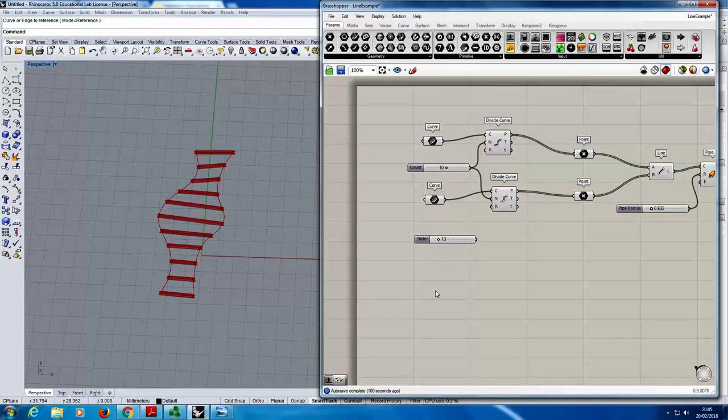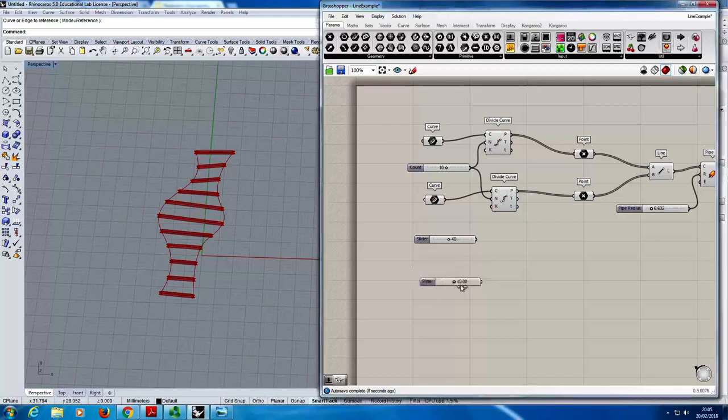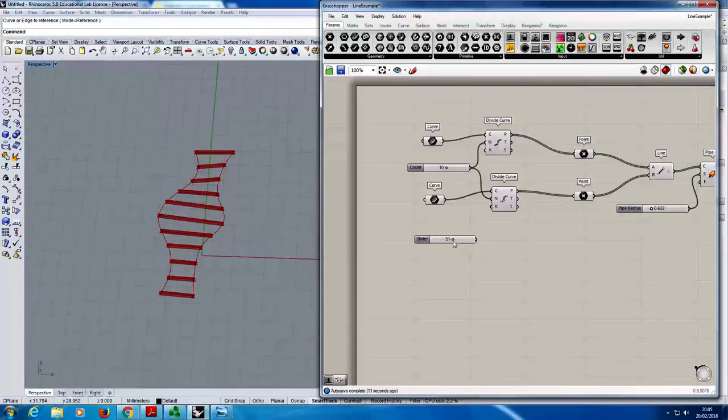So in this case 13, that's its initial value. It's got the accuracy to the number of decimal places you specified. So if you put in no decimal places, as in this case, it will set the slider up to only snap to whole numbers. If I was to type in 13.00 instead, then it would give me 2 decimal places and so on. And it will also set up what it thinks is a reasonable range around that number, basically the order of magnitude that number is in.